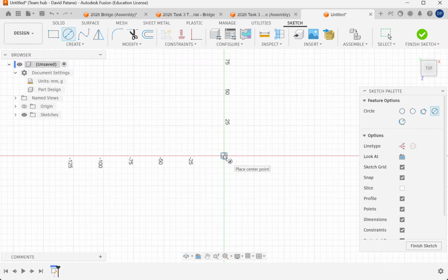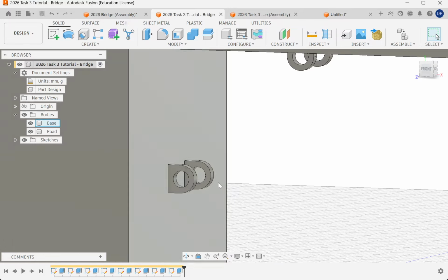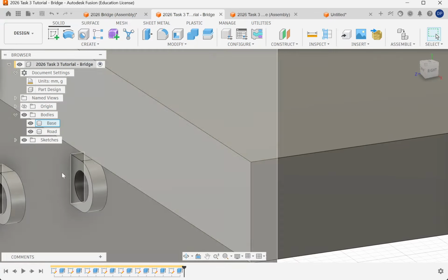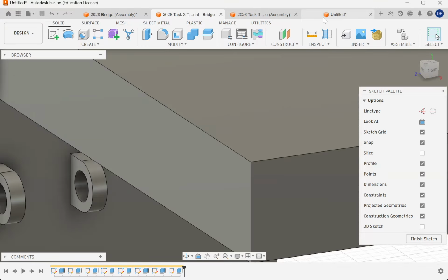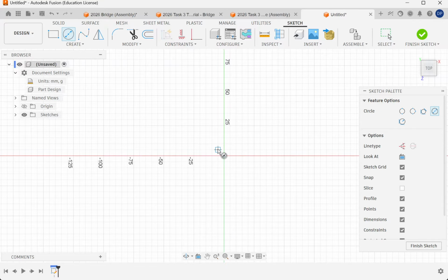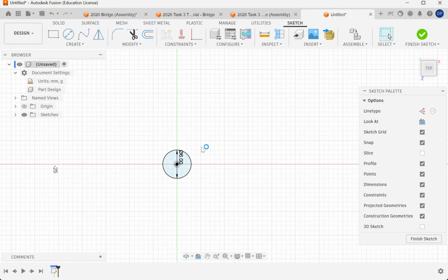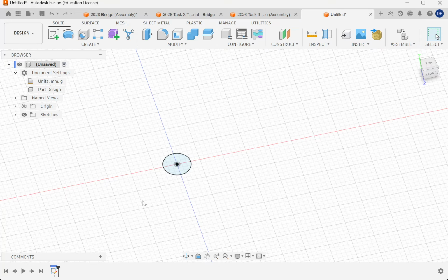And I also know from when I did my gap in my support that we had like a 7mm hole there. But sorry, by gap in the hole, I meant this thing over here, this gap between these two is 7mm. So I want to make it look like it fits inside there because it's going to look nicer. So let's just pick a number. When we do our circle, I want it to be 6mm. 6mm is the cylinder. I'll press OK.